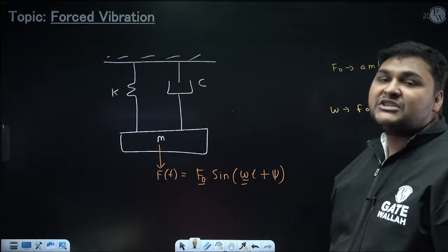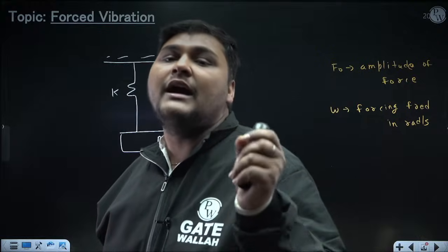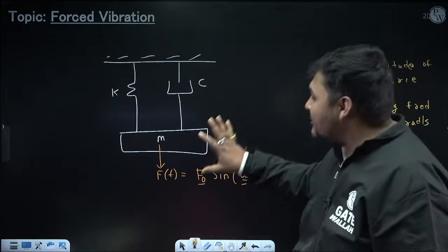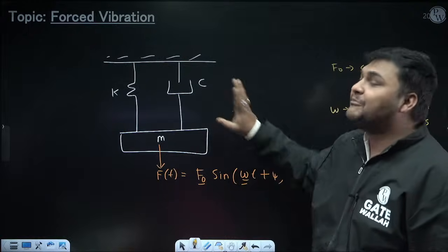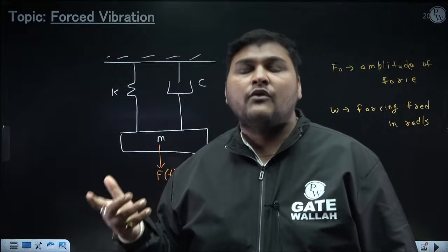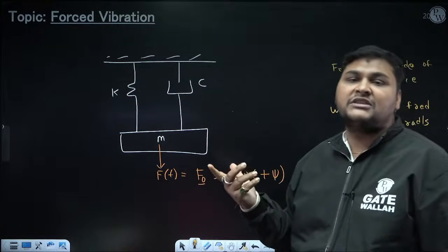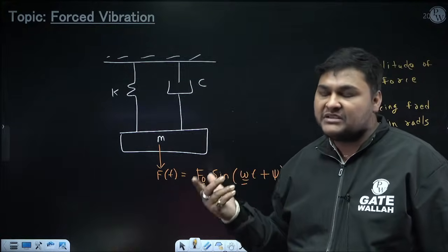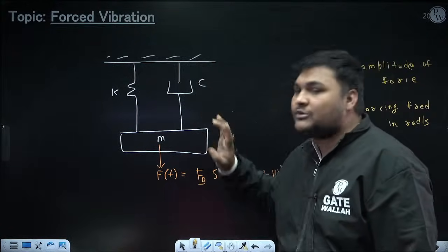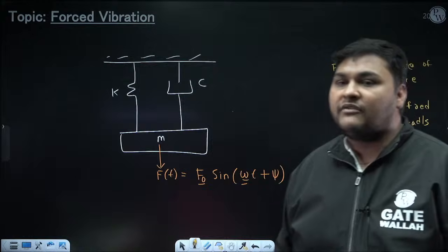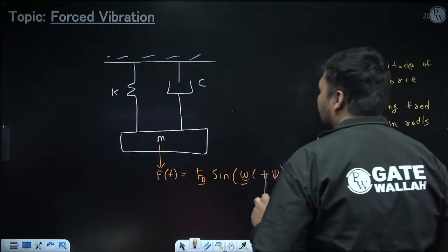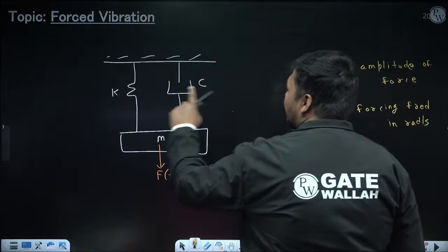But if the examiner is giving natural frequency or natural undamped frequency, natural undamped frequency means if in this system free vibration is occurring and no damper is attached, then the frequency of that vibration is the natural frequency. And we know for the general case the formula to calculate natural frequency, that is omega n, is root k by m. If it is another case, the formula will be root ke by me. But what will be the frequency of this vibration? That we will come to know after derivation. So to find the solution for this case, first we will find its governing equation.